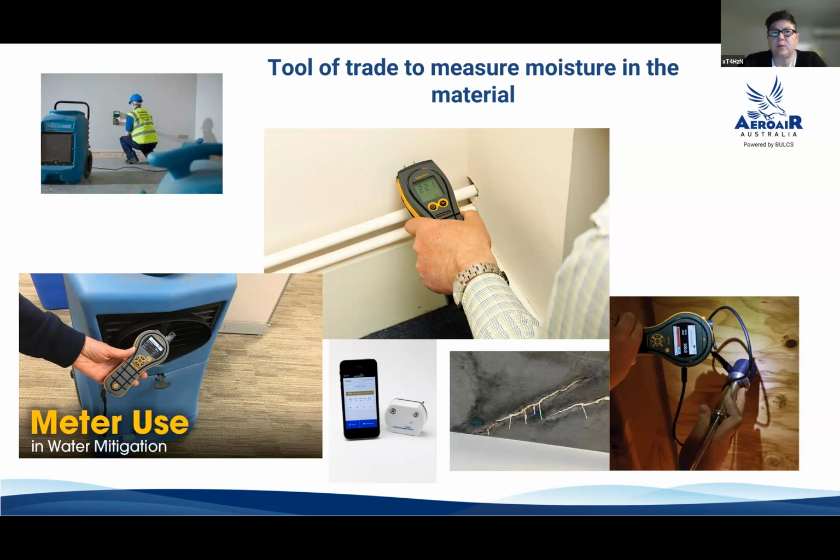Or if you have brick veneers, some of them have chicken wire at the back that holds up the insulation. If you scan with your non-penetrative moisture meter and get 100% throughout equally, it may not be a moisture issue. It could be just a material at the back end that has it.